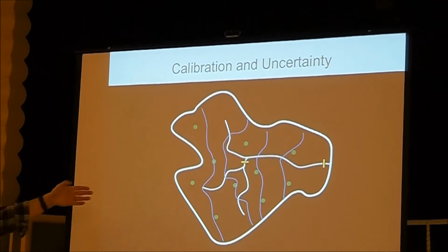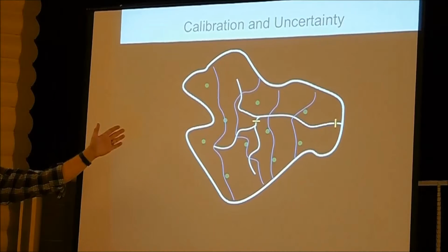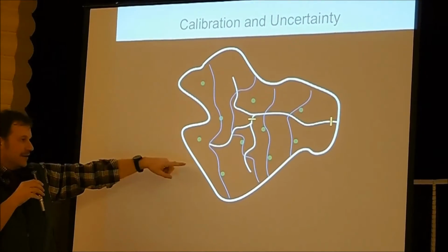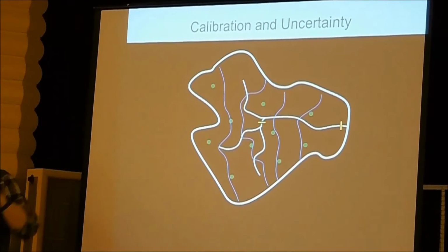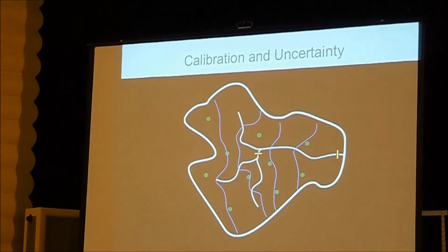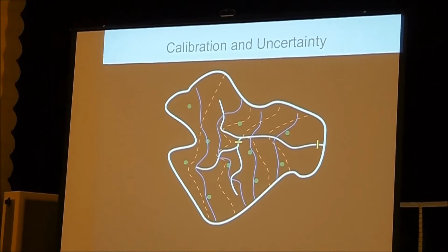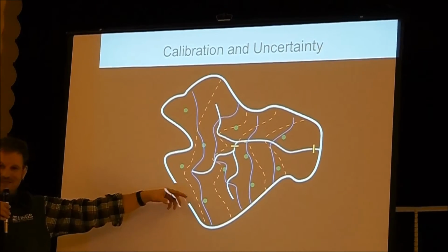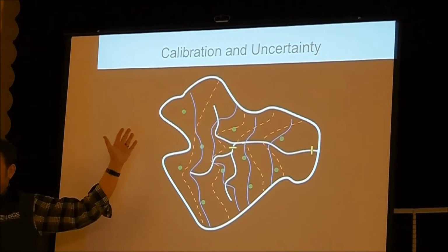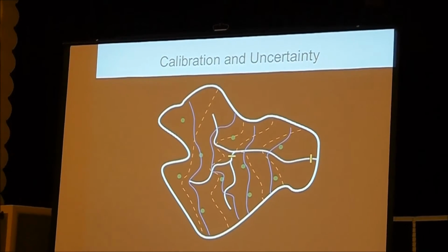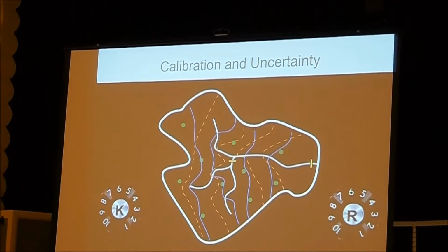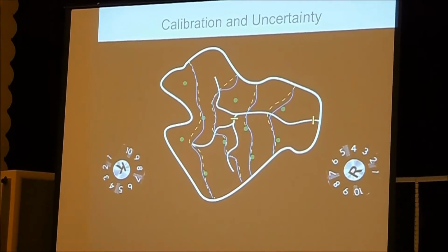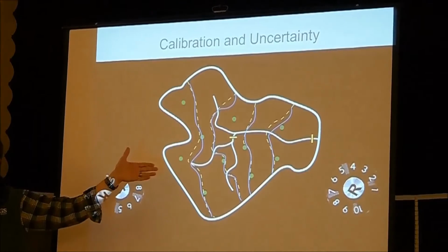And now we have these contours of the water surface, of the water table surface, going from high to low. That's what the blue line here is. That's what we've measured. And so we use a set of parameters, and we run the model, and we get this. It's kind of the right planet. It has similar behavior, but it doesn't match all that well. But the parameters can act kind of like little dials here. You twist those dials around until you get your data to match what the model is telling you.